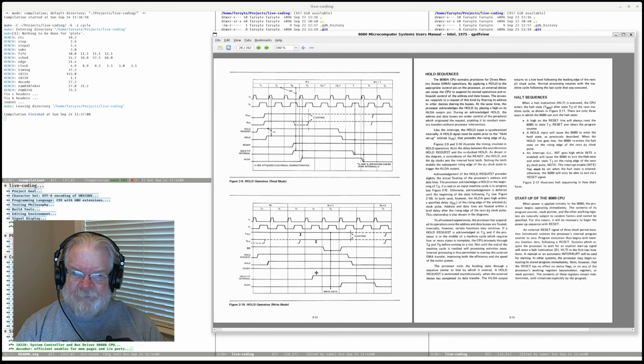Here in M2T1, we are asserting the address bus, and sync goes high, and then sync goes low in T2, and dbin goes high, and there's byte 2 of the instruction coming in. And now the actual hardware, it just sits there on the data bus until T3 where it gets stored. So looking back at this, how long is it likely to stay there? Well, that's going to be the descending edge of dbin there in T3. Okay, there we've got it.